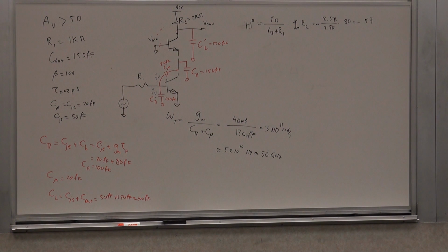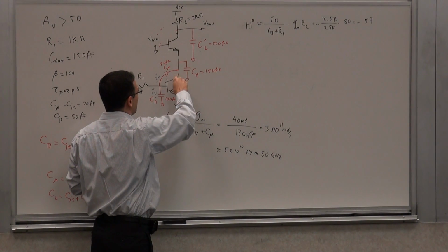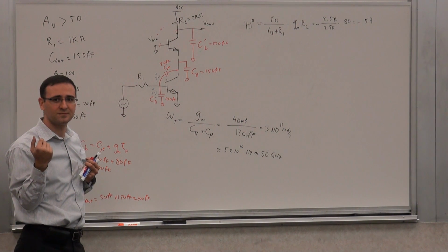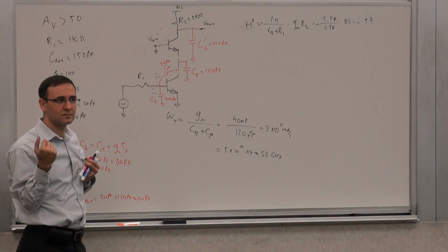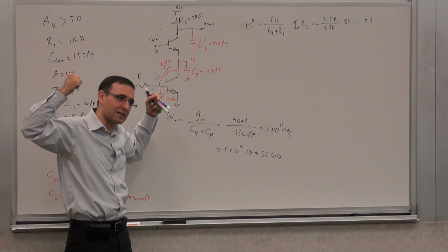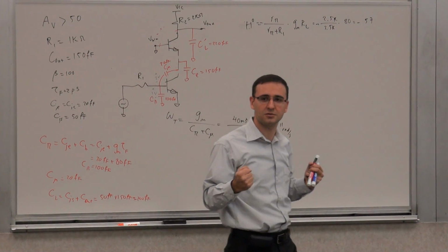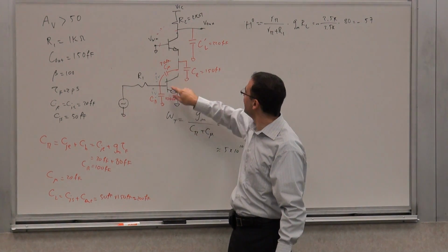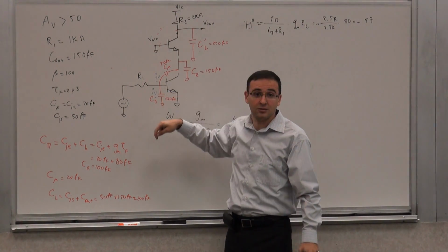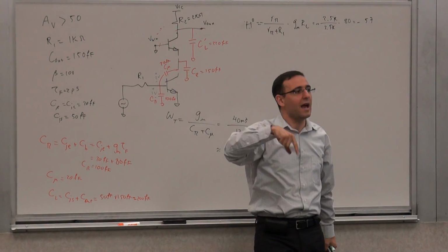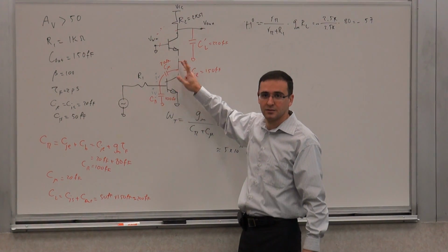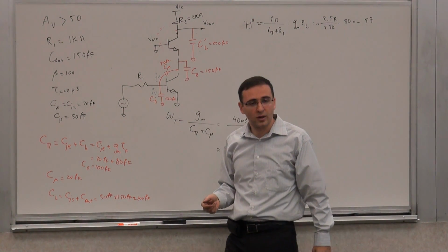So now, how many poles? 3. I have a capacitive group here, which basically eliminates one of these, so I have 2 here and 1 there. So 3 poles. How many zeros? How many capacitors can I simultaneously short circuit and get a non-zero transfer function? Still 1, right? Still it's this guy. Because if I short circuit this with anything else at the same time, this will kill the signal. This is the only one, so there's only one. And again, since it changes the polarity of the gain, because the gain from here is an inversion, it's a right half plane zero.